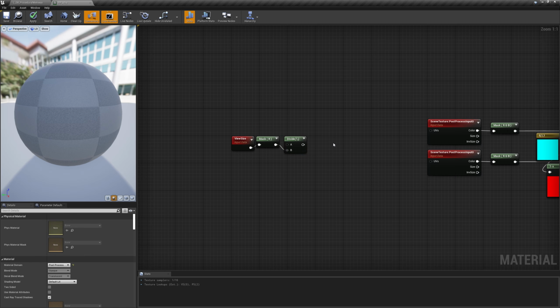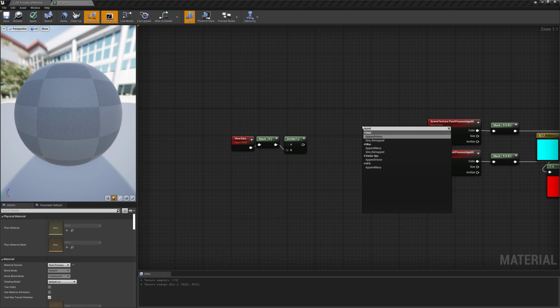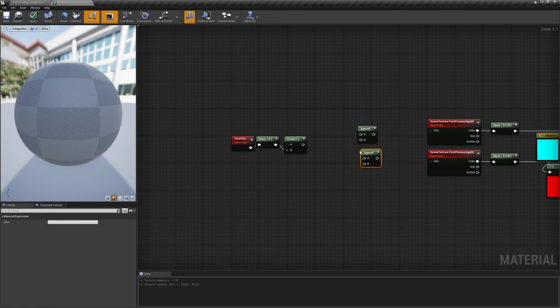The result of this operation is the amount to add or subtract from the UVs needed to move the image by exactly 1 pixel on the left or on the right. In other words, it is the pixel width in UV space. Let's use it by adding this value to one of the scene UVs and its inverse to the other one, once made it a vector 2.